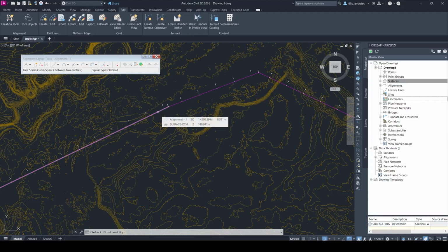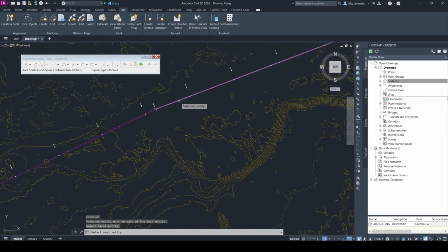So first we click one, and second we click by the left mouse button the second one, and the software is asking us which angle of our curve solution will be the bigger one. So the greater than 180 degrees or less than 180 degrees. So basically it asks whether I must design the curve here or here. We need the curve from this side, so less than 180.